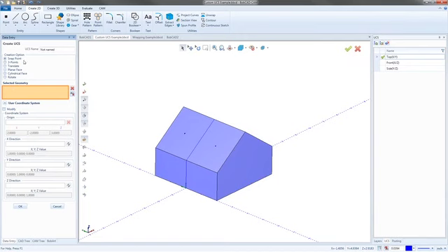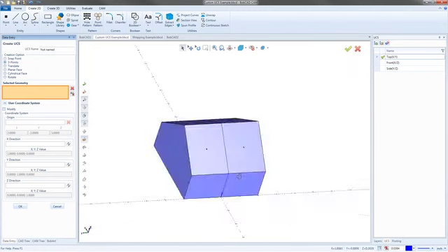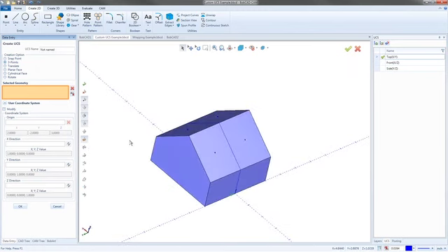So the next one we have is probably the most underutilized function. I think a lot of people jump right past it, and it's a really, really good function for setting up custom planes. What it gives me the ability to do is set up a custom plane based on 3 points. So I can define the Z first.